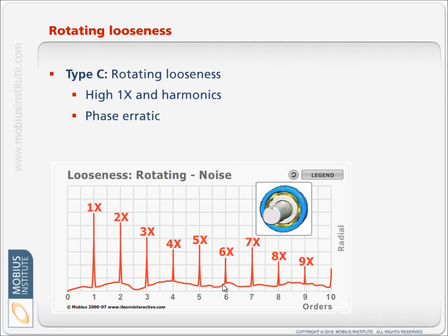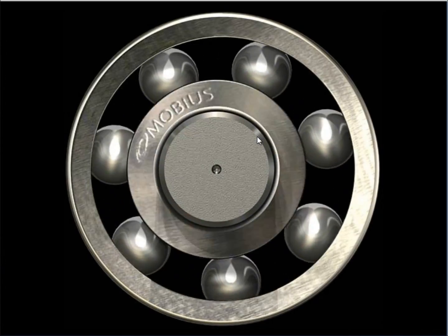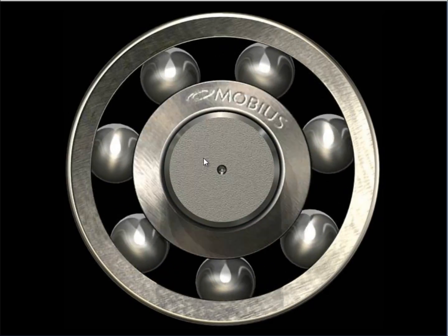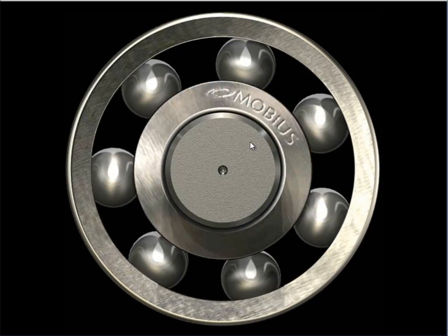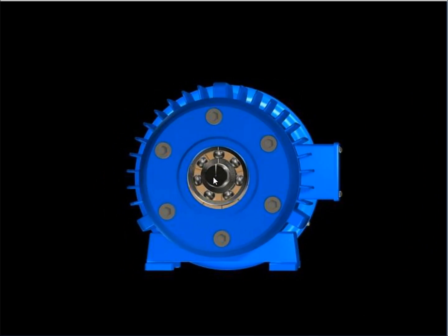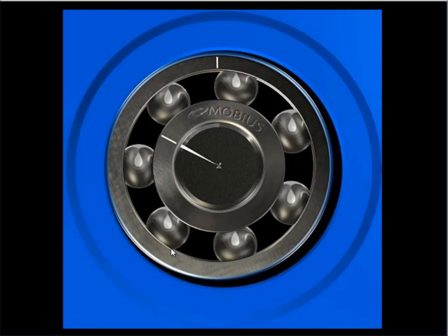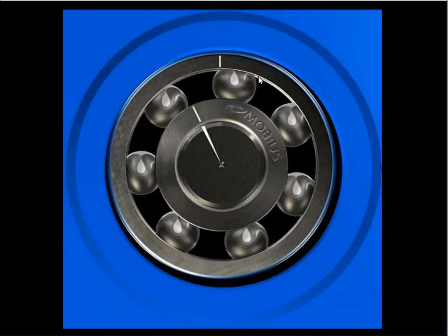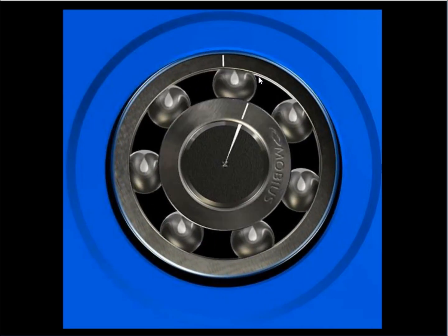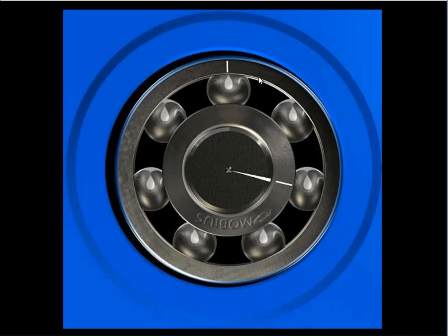One of the keys is not only do we see a lot of harmonics, but often the noise floor raises up. Because of the impacting, we cause resonance and the noise floor can move up, because we're causing so much noise. So this is one attempt at the sort of vibration we might be having, where there's enough clearance and it's just bouncing around in there. Here's another case where the whole bearing is moving within the housing. Obviously these animations are exaggerated in terms of the amount of clearance and the exact motion that would be observed, but the bottom line is we'll see all the harmonics, and that's an indicator of this type of fault.